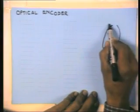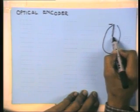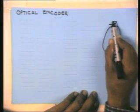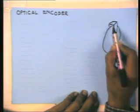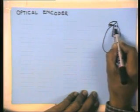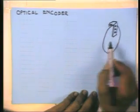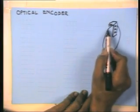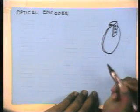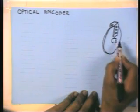and on the disk what we are doing is placing some diodes which will emit light, and we are putting some sensors. So let me put, let's say, 3 sensors here. On the other side, which is not seen, we have the source of light, and this is the shaft whose angle we are trying to measure.